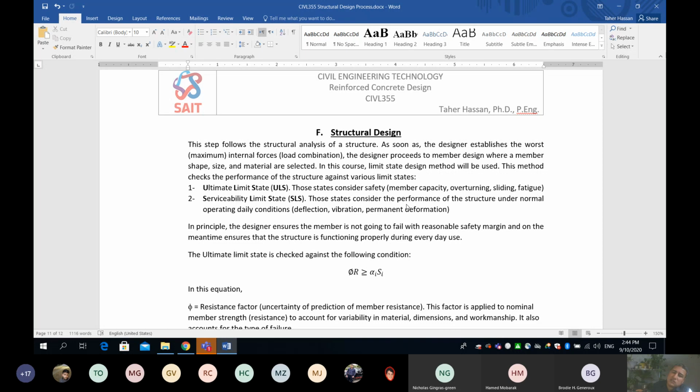If you have so much deflection, the design of the beam is not enough to carry the dead loads and live loads. You're also still confused. The beam is still alive, still didn't fall to the ground. Nobody's gonna die. However, it's about everyday life. I'm talking about deflection, which is serviceability limit state. When we have so much deflection, how can this affect our daily life? We have one example, pipes will crack. What else can go wrong?